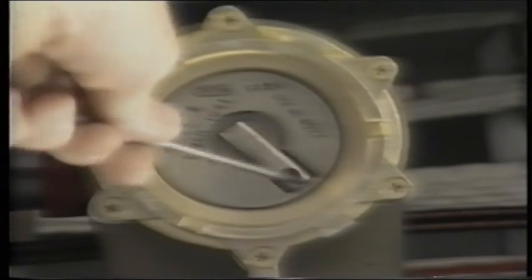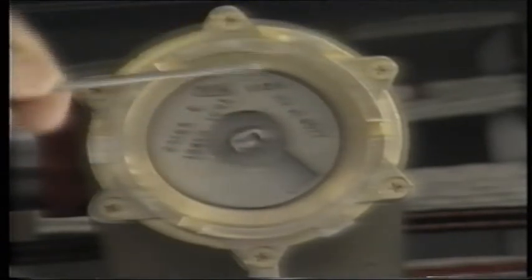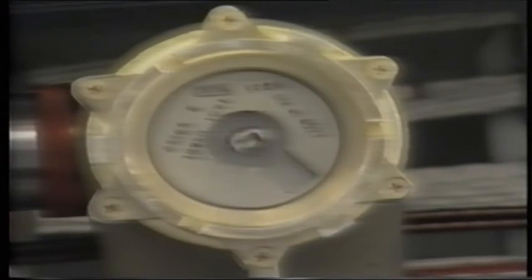At times, it may be necessary to defuel the airplane or an individual tank to perform maintenance. This is done by using controls in the flight deck and at the fueling control panel. Defueling begins by repositioning the defueling tab in the fueling receptacle. The defueling tab unseats the check valve in the receptacle so fuel can be pumped overboard. Then open the manual defueling valve. It connects the fueling manifold with the cross-feed manifold.